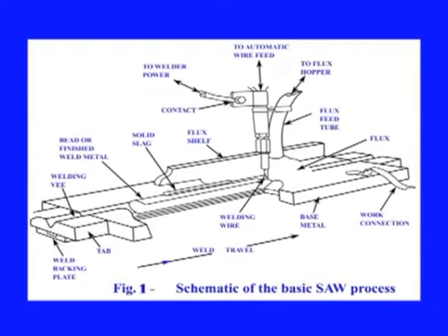Thus, this will be moving during the welding process. So, in this particular case it is being shown moving from this to this, and therefore the welding will be carried out, or the fusion of the material will take place, along this travel of the welding wire, and this flux will cover the arc at this point of welding.